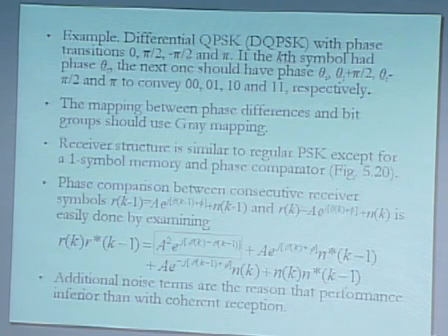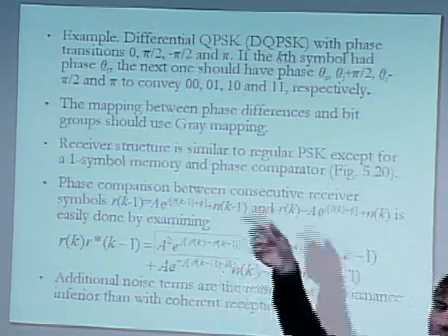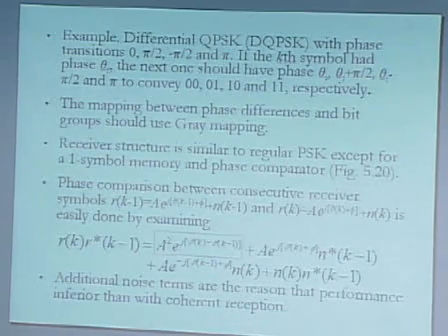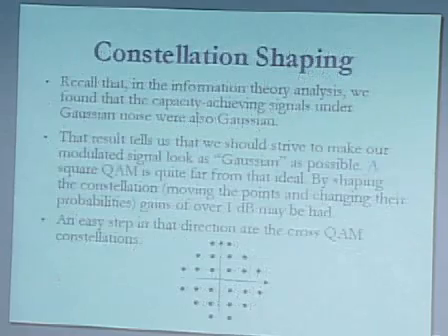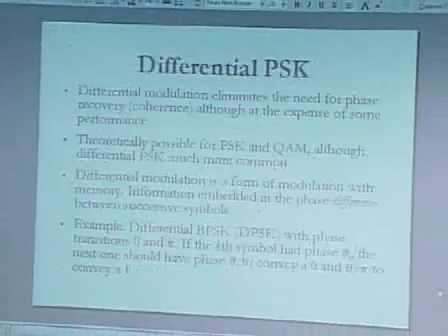But you have the simplicity that you don't have to make sure, to recover the theta, that this theta here is the same that you had at the transmitter. It just can be whatever you want. Okay, so that's it in differential PSK.